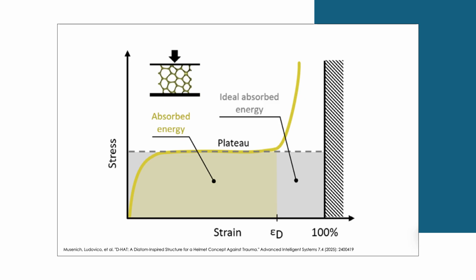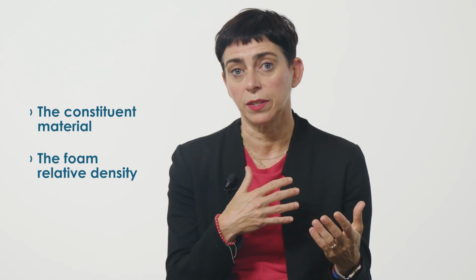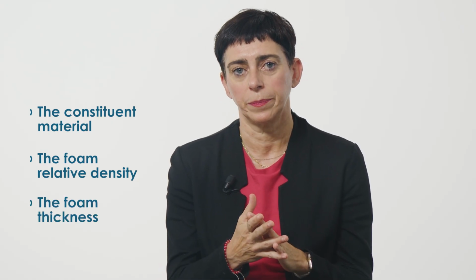Energy absorption efficiency is highest in the plateau region. In fact, energy absorbed in the impact is represented by the area under the stress-strain curve, which is maximized by a wide plateau region. An ideal foam absorbs the induced energy in the plateau region without densifying. This area can be tailored by modifying the constituent material, so choosing a different foam, the foam relative density, the same foam can be manufactured in different densities, or the foam thickness.